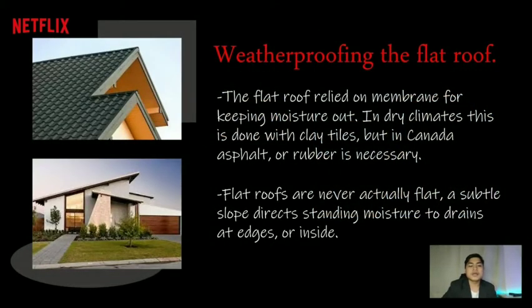Weatherproofing the flat roof. The flat roof relies on a membrane for keeping moisture out. In dry climates, this is done with clay tiles, but in Canada asphalt or rubber is necessary. And it is also never actually flat. A subtle slope directs standing moisture to drains at the edge or inside.